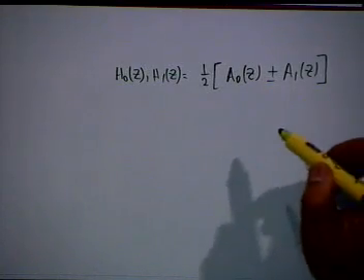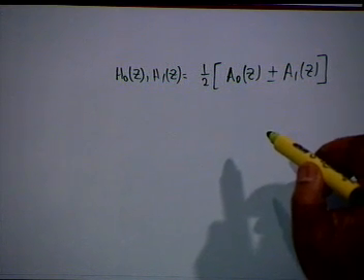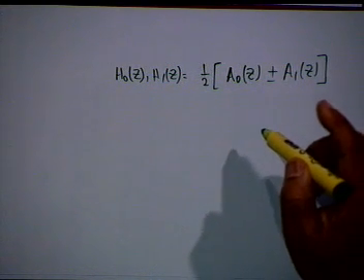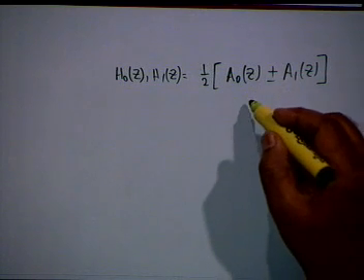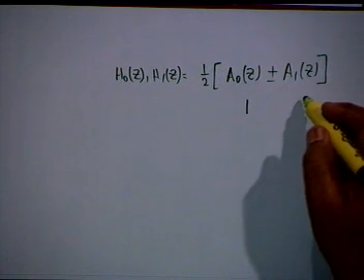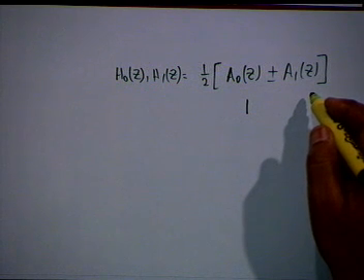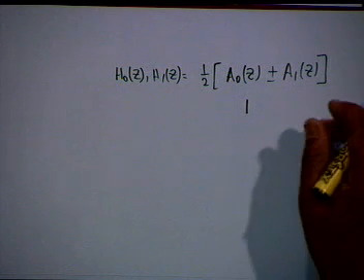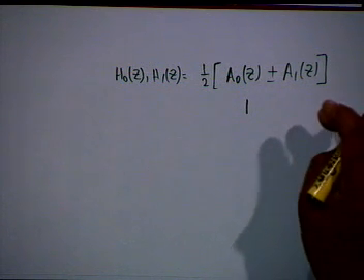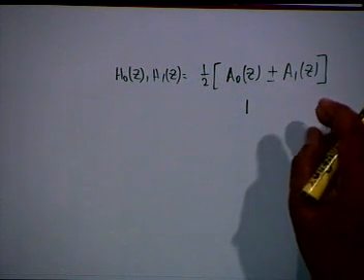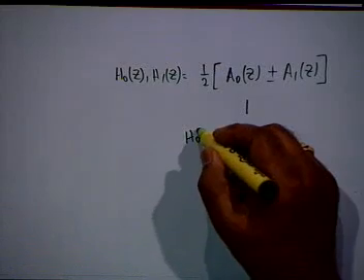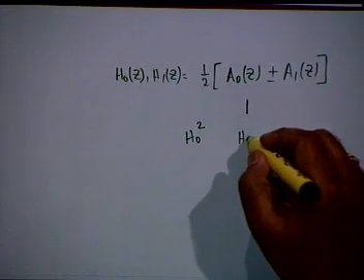All that you have to realize is A0 and A1, two all pass functions. And we took a particularly simple and interesting example of A0 being equal to 1 and A1 being equal to a first order all pass, which gives a very versatile realization of several kinds of filters and also a magnitude complementary pair by taking H0 squared and H1 squared.